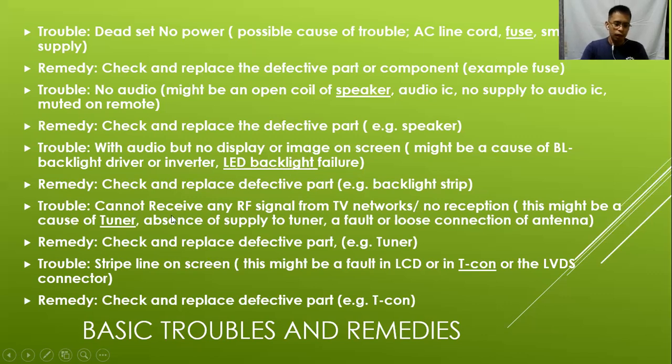Another trouble, cannot receive any RF or radio frequency signal from TV or television networks, or we call that no reception. This might be a cause of tuner, absence of supply to tuner, a fault or loose connection of antenna. Kung nagluwag yung antenna, higpitan. Kung wala yung supply doon sa tuner, nag-voltage test po tayo.